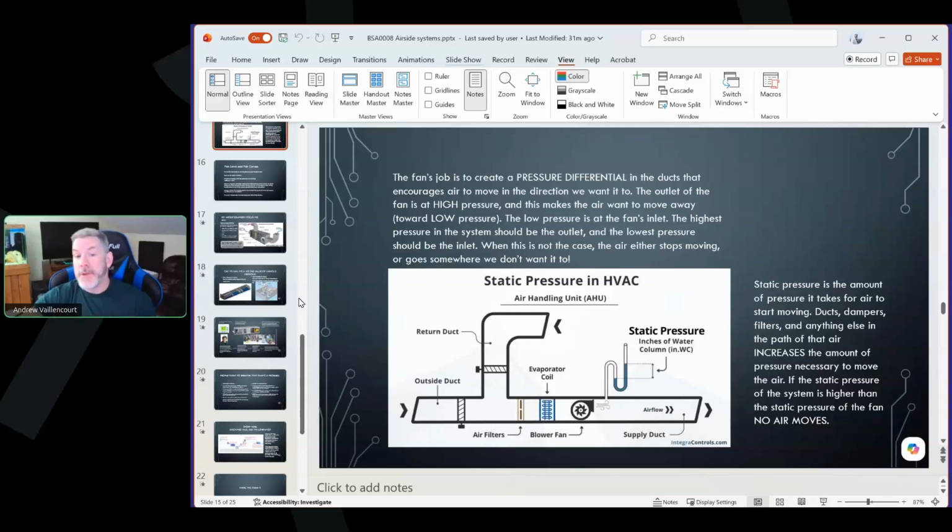So in any given building, you are going to transfer energy to and from places in and out of the building. And you're going to use media to do that. In this case, in an airside system, the heat transfer media is in fact air. That's why we call them airside. This is in juxtaposition or opposite of waterside systems, where we're going to pump water around.